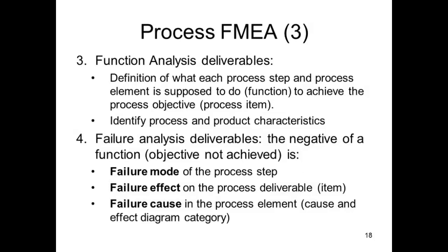Failure analysis, that's pretty much self-explanatory, and that includes the failure mode, the failure effect, and the failure cause. Basically the negative of a function, namely the objective not achieved, is the failure mode of the process step.